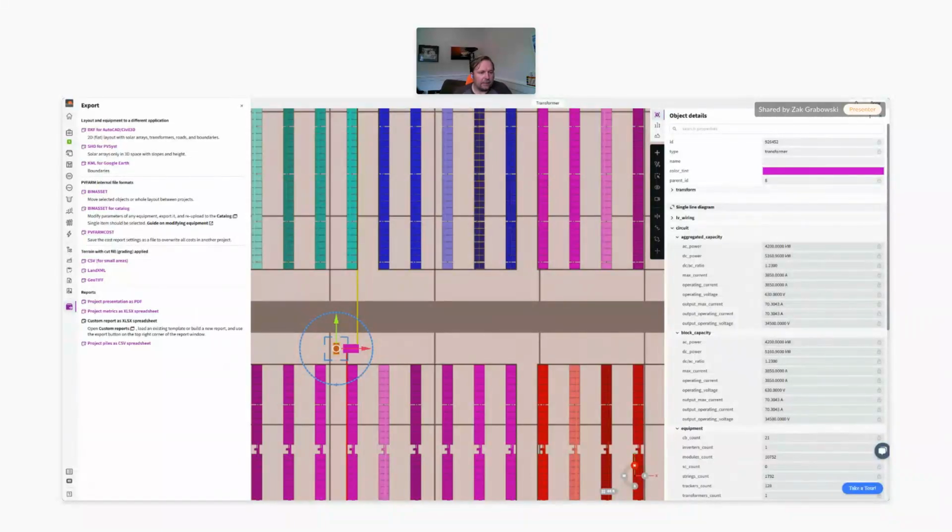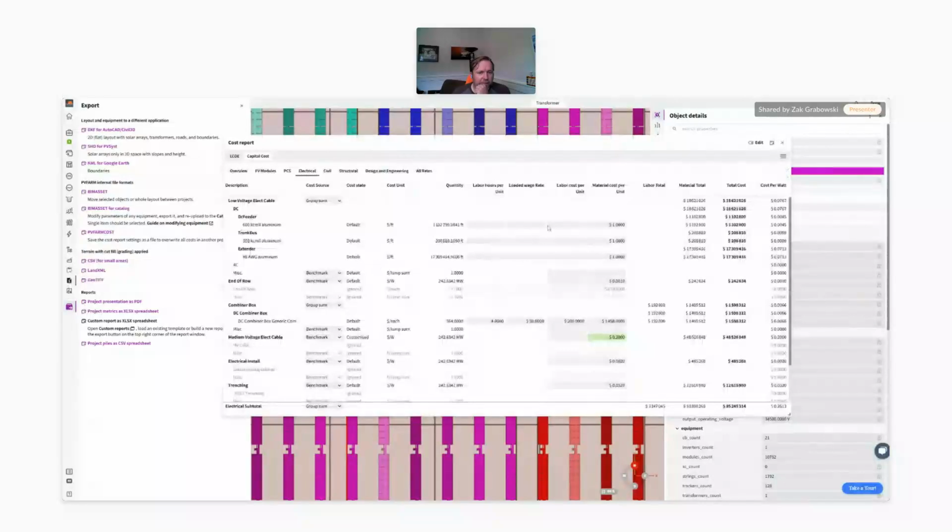So the costs are calculated based on items that are in the model. And the user can then input specific costs. What you'll see here is for DC feeder, for example, we have 600 kcmil. If I had other sizes, they would also show up under DC feeder. I see I've got 1.1 million feet of that cable, and I just have a cost to it as well. So that gives me then a total cost.